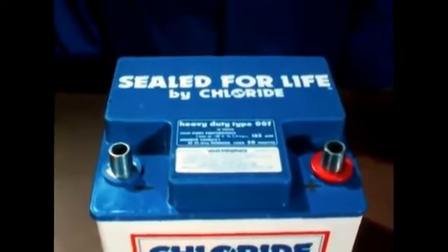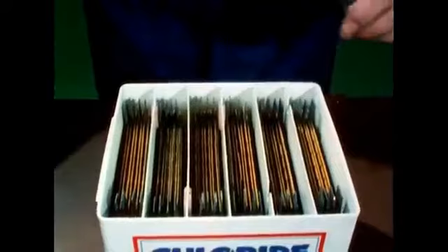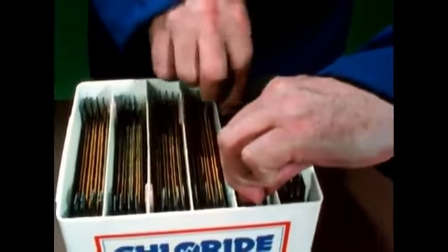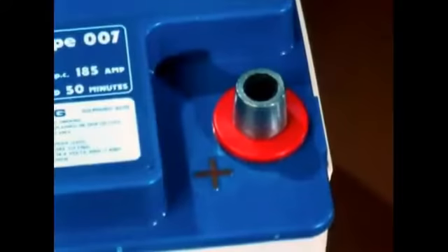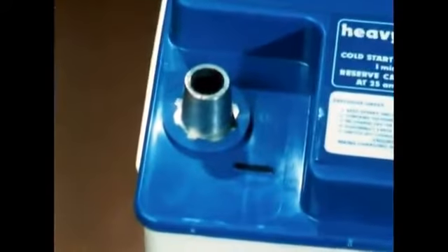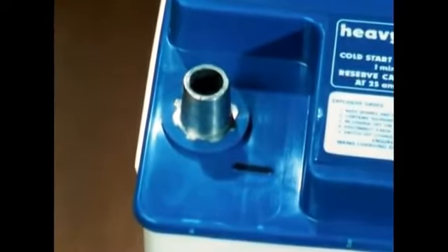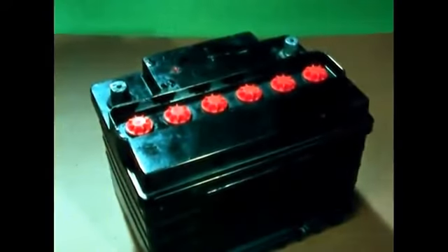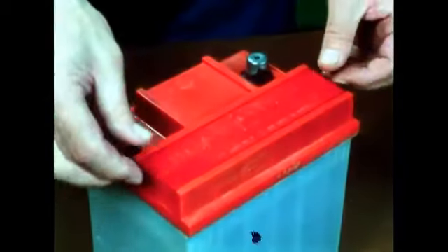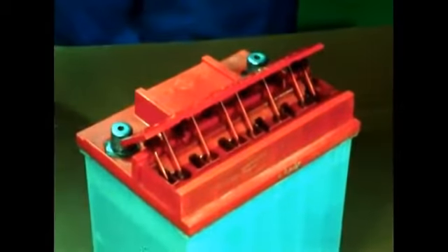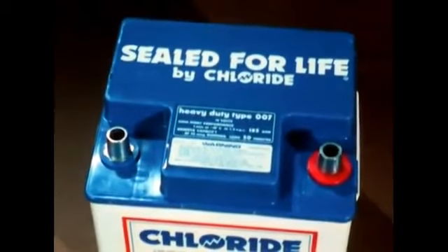In order to get a worthwhile amount of electricity out of a cell, the plate area needs to be as large as possible, so that plates are made with this in mind. Several plates of each sort are connected together, and the interleaved separators make sure they don't touch. Usually the positive and negative terminals are clearly marked. And sometimes there are caps which can be unscrewed for adding distilled water. A vent in each cap allows any gas produced during discharge to escape. Other designs have different adding water systems. And the most modern batteries never need adding water at all.